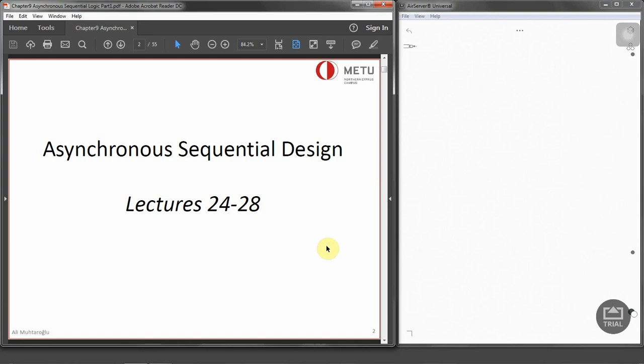Asynchronous circuits are harder to design due to potential instability issues and the timing problems involved in the feedback path and so on. As we already said, the change of state occurs immediately after the input changes. So when we are designing asynchronous sequential circuits, we need to be very careful that each new state keeps the circuit in a stable condition even though the feedback path exists.